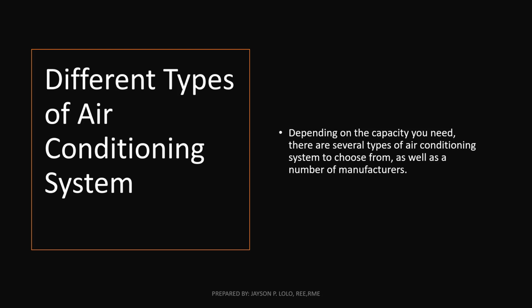But remember that there are more expensive systems such as VRF or VRV, and especially the ducted systems, and they are made up of several indoor and outdoor units. The indoor units are installed above the ceiling, leaving only the grills visible. So they are common in large commercial facilities, and they are applicable to hospitals, hotels, and office buildings.